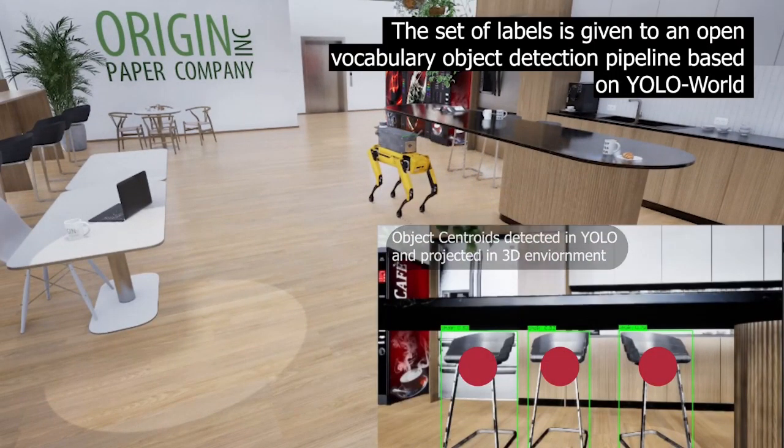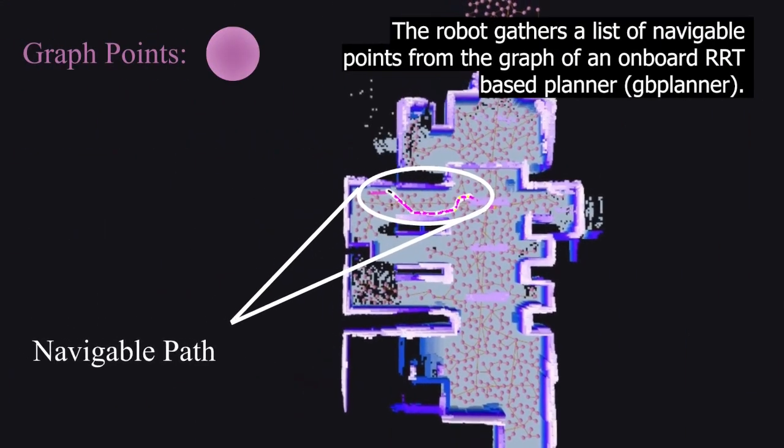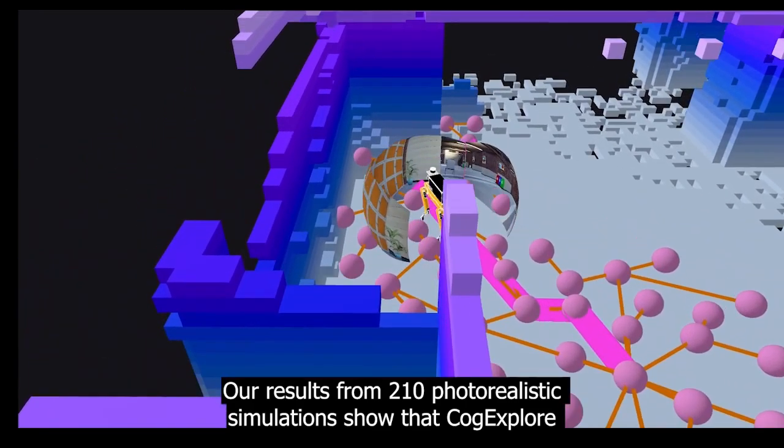The set of labels is given to an open vocabulary object detection pipeline based on YOLO World. The robot gathers a list of navigable points from a graph of an onboard RRT-based planner. Our results show that Cog Explorer outperformed a state-of-the-art heuristic-based planner.